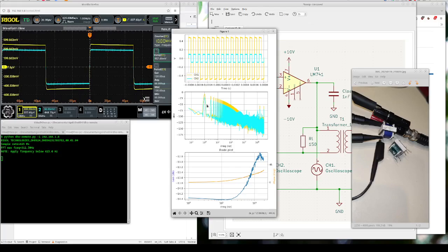And since channel 2 is smaller, you see a negative. So it is about minus 15 dB, 14.4. And 15 dB I mentioned because that's 5 times. So I assume this is a 1 to 5 transformer. I drive the input, and the output is 15 dB lower. And that's good, because that means that the input is high impedance and the output is low impedance. And the output is what we want to put in series with our scope.